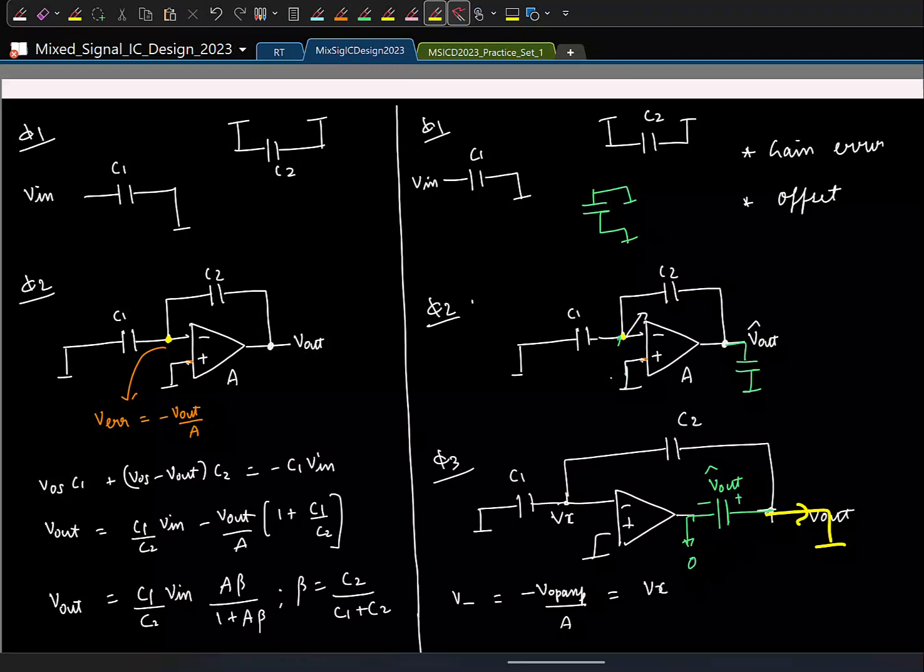Yeah, you are right. So there are some other additional considerations. I'm not going into details there. Basically, usually in most of the applications, the load capacitor might not be really large, as we see in ADC cases. If this has a large enough gain, the load capacitor will usually not be very large, and you can work it out and see. I'll refer you to the paper, but what you mentioned is a problem. But let's not worry about that for now.